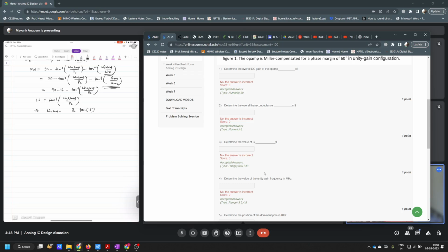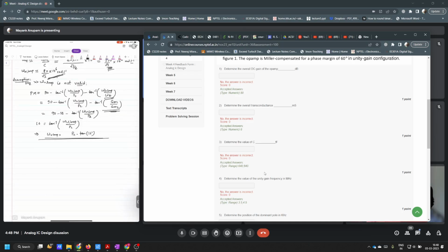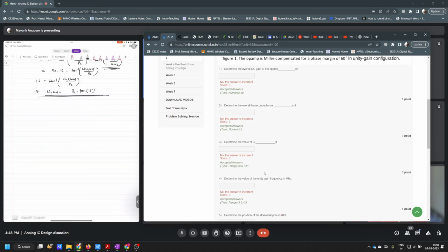Yes, sir. What was the doubt? The doubt is that if for the equation of omega u, we put gm1 by C, and in p2 also we put that approximation of gm2 by CL, the answer will come to nearly 900 femtofarad. But the answer is 640 to 840. So basically, the approximation is not valid.